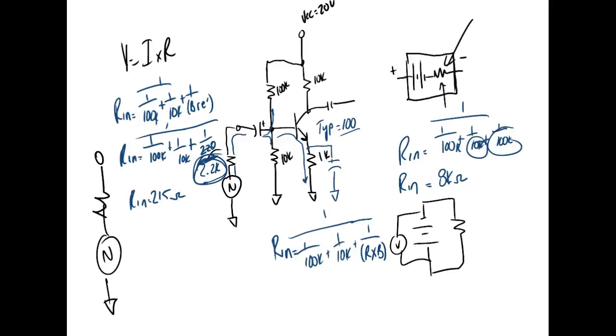And the circuits are fairly simple to hook up. I'll leave this up so when it comes time for y'all to start hooking these amplifiers up. Basically, this is the last lecture on bipolar transistors, or the common emitter. What we'll do was look at the common base, but you're probably never going to run into a common base because all you get out of a common emitter. So the characteristics of a common emitter: a fairly low input resistance and a fairly high output resistance.